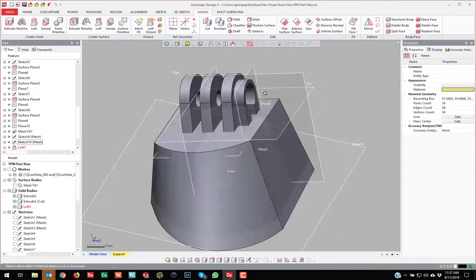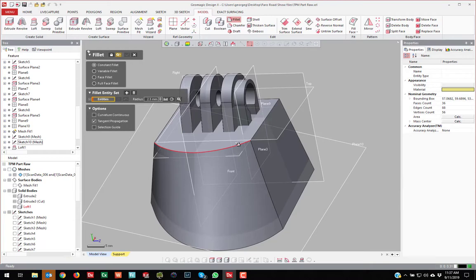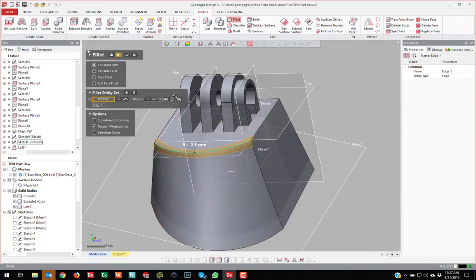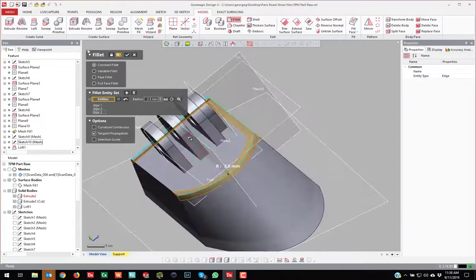And then obviously there are fillets on there, so we need to come in. Now if I select an edge and I hit this estimate from radius, it'll look at the underlying mesh and calculate what it thinks the radius of the mesh is. And then you have the ability to come in and override it, which is usually what we do, right?